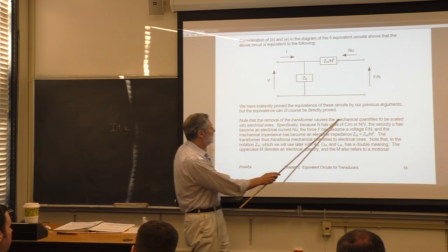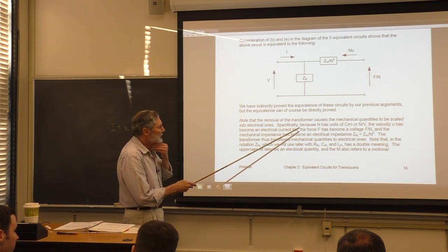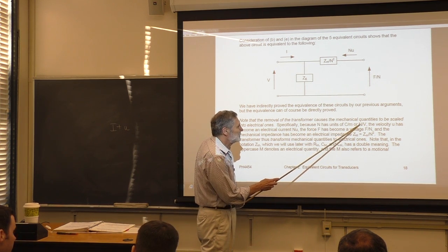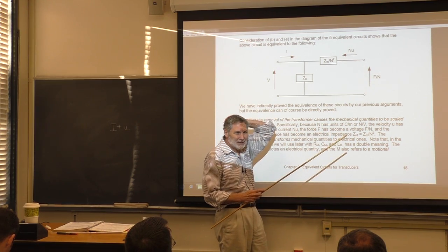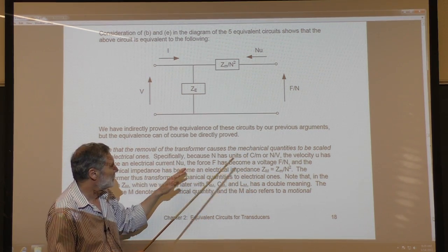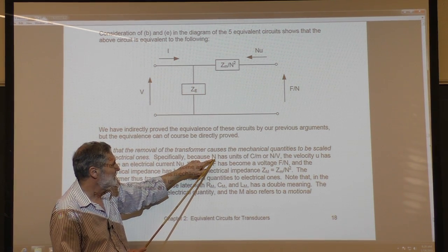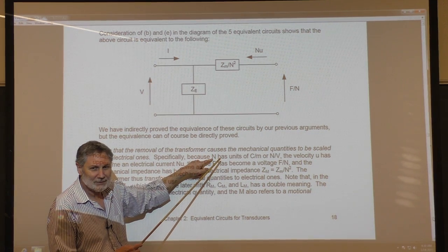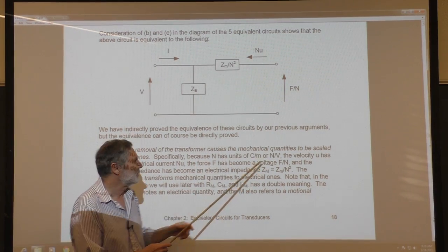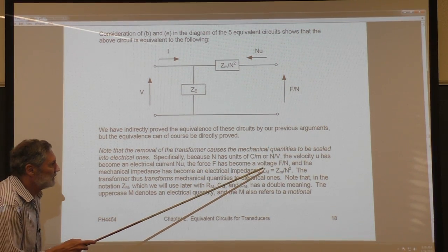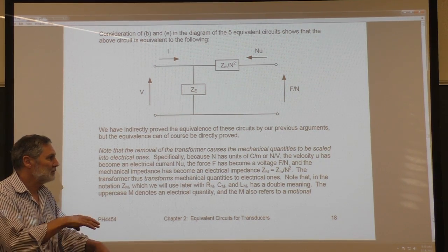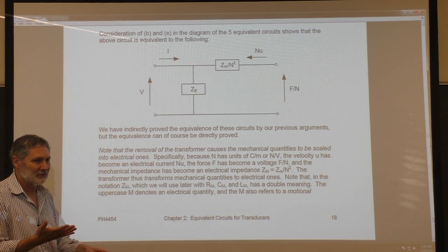So here is just a restatement of what I've said, and I'm going to be editing this. You can show that the units of N are newtons. Now we have to be careful here. You've actually encountered this before, and you might have missed it. Most people don't see it, and it doesn't bother them. But here, sitting alone like this, is this complex dimensional ratio of turns thing. This is newtons here, so don't get confused. You can show that N has units of newtons per volt. So it's a conversion between mechanical force in newtons and electrical force, or voltage, in volts.